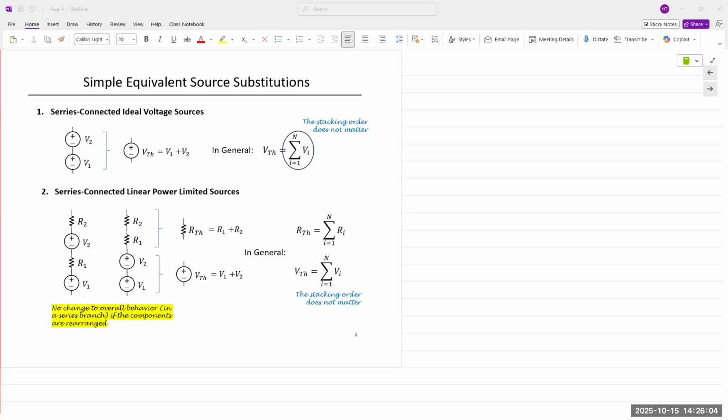If you were to perform this in the lab, the measurement part is actually easy. It's the theoretical part that takes long. So let's say we have a circuit comprised of one voltage source and five or six resistors, right? And we have a pair of terminals where we are trying to find the Thevenin circuit. If you have two terminals that are open, you have to determine the Thevenin circuit between that pair of terminals. All you have to do is measure voltage, measure resistance, and measure the current between those pair of terminals.